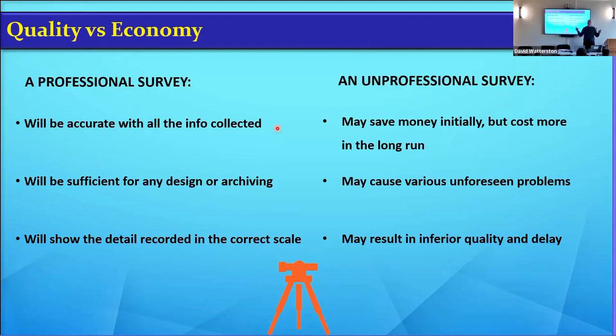Now, if you find it's within 100 mil, 200 mil, it's good enough for doing your preliminary design. And you don't have to spend a load of money trying to get surveyed. But if they want to go ahead with it, then you can get a survey in. And then at least when you get the survey, you'll get something independent to check against that survey as well.